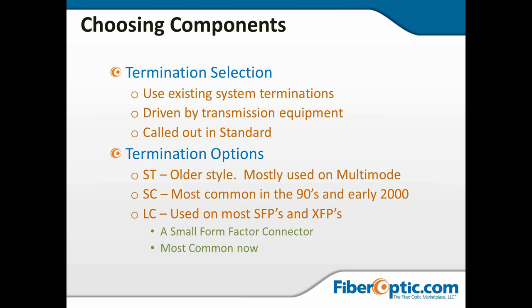Then you've got the LCs. Most SFPs and XFPs today use a duplex LC connector. It's the small form factor connector, uses a 1.25 millimeter ferrule, and the slide here says it's most common now.